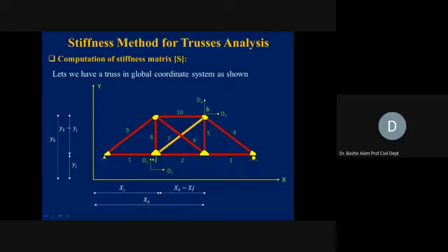And for that D1, we will call DM1, because we need to now differentiate between this D1 and the member axis, which is DM, displacement along the member axis now. So this will become DM1, and perpendicular to this, which is the local y axis of this member, that will become our DM2. Similarly, at this joint K now of this member 7, along the length of this member, it will become DM3, and perpendicular to this, it will become DM4. So those are the displacements now.